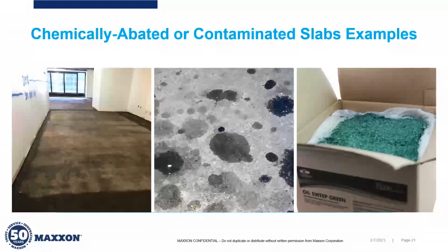The third slide, the third picture there is just of some oil-based sweeping compound. I mean, there's been situations where at the end of every job site, the GC has somebody sweep down that space, and they use these compounds to keep dust down, and they really don't understand that every day that they use this product, they're basically contaminating the surface that the floor covering installer now has to deal with when he goes back to install floor covering or prepare that floor.